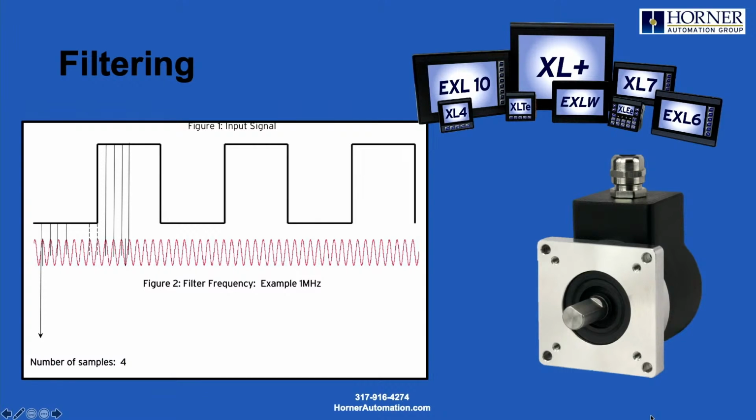So you'll not only configure a frequency at which you want to sample, but you'll also configure how many consecutive ones are going to actually represent a valid pulse. In other words, I'm expecting a pulse of X width, and I'm going to sample it at 4 times the frequency, and let's say if I don't get at least 4 consecutive ones in a row, then I'm going to assume that that's noise and not a valid pulse.